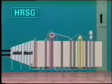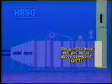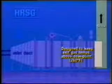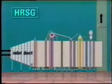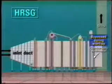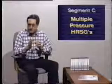Normally, the HRSG is designed to keep exit gas temperatures above the dew point, about 260 degrees Fahrenheit or 130 degrees Celsius. But this may be difficult to achieve during startup. For this reason, in some installations, the condensate preheaters are bypassed during startup. We'll be talking more about this in the next segment, which looks in detail at the condensate and feed system.